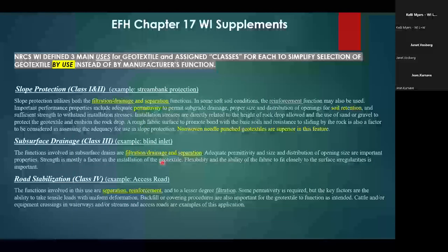Subsurface drainage, that one's pretty obvious. Filtration and drainage, holding the soil in place and letting water through, are its two key features, but also separating, maybe, a granular material, drainage rock, from the soil beneath it. Strength is not so much of a factor for subsurface drainage. You more want something that is going to be able to let water through. That's what you're looking at there. And I'll talk a little bit more about how you decide this one's better than that one as far as letting water through. We'll get into that here in a minute.